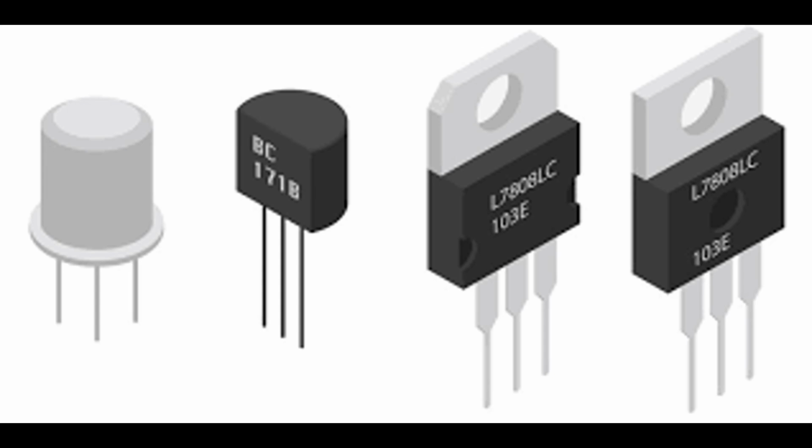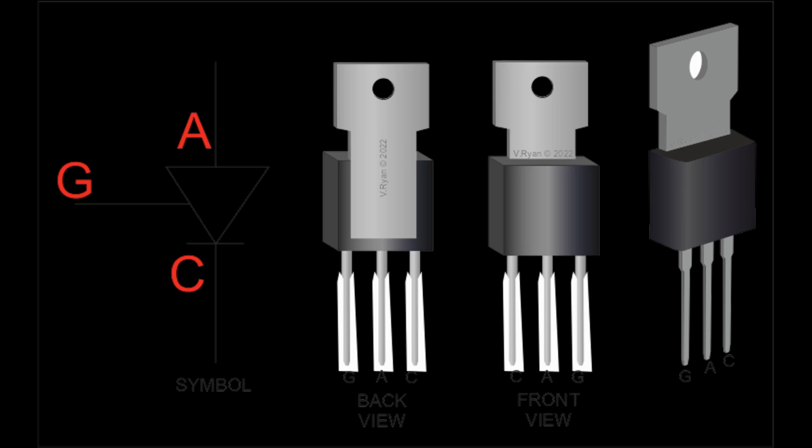Motor control. The MCT conducts, providing power to the motor and controlling its speed by adjusting the frequency of the AC supply. Turn-off signal. A negative gate voltage is applied to turn off the MCT, stopping the current flow to the motor. Precise control. The gate drive circuit continuously monitors and adjusts the gate signals to precisely control the motor's speed and torque.